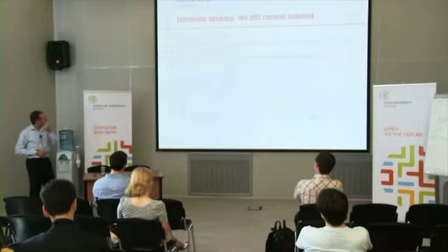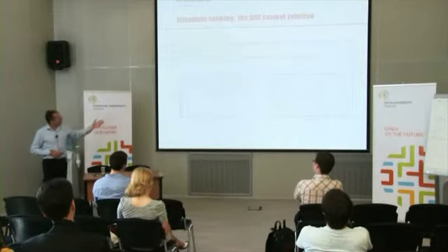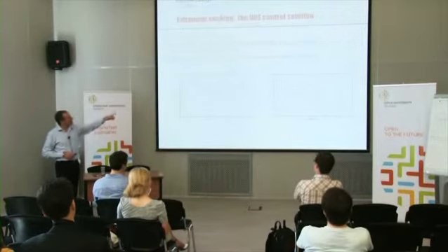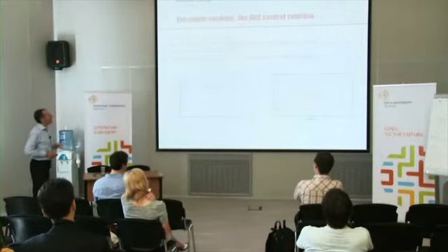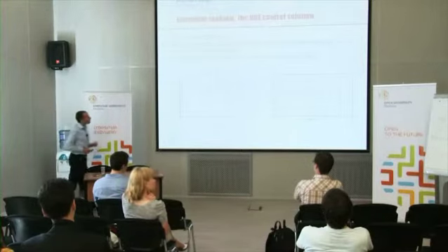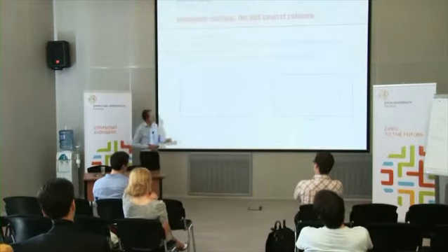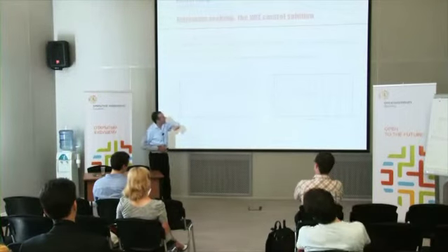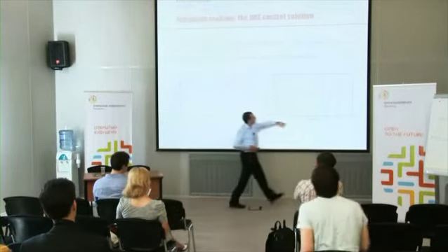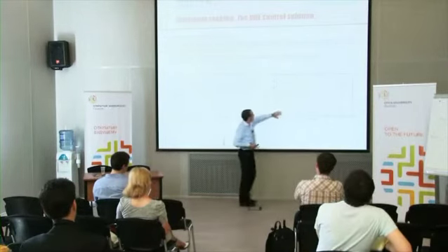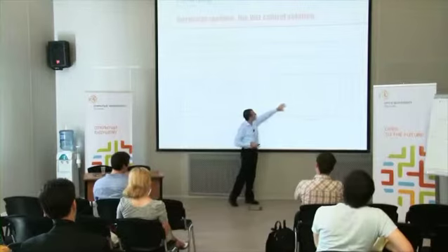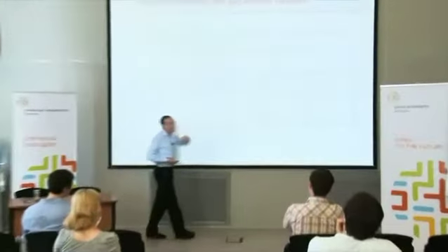And so some data. To the right, we have that as a function of the temperature, you see that you have a map of the amount of steam that you produce, and typically you would like to use your turbine around the maximum, which is approximately this 38 line here. Okay, so this is the point where you want. And typically, this means that your extremum seeking algorithm, starting from some temperature, should move close to that point.